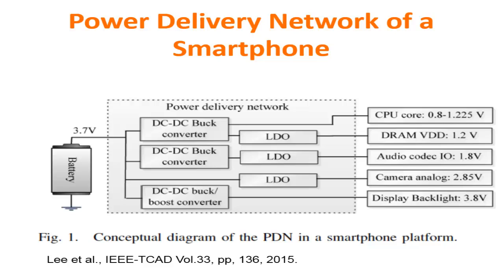You probably remember that we have discussed together that the power consumption of a digital circuit is something like 1/2 the total capacitance of the circuit, times the supply voltage squared, times the frequency.